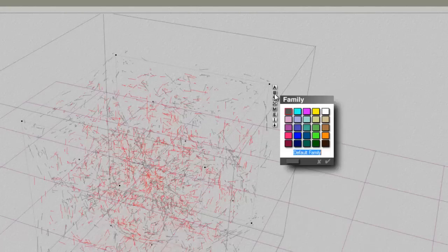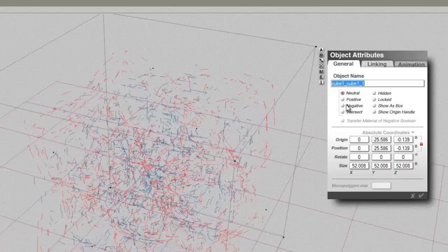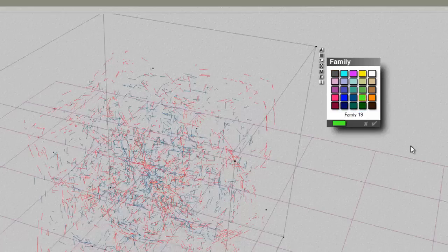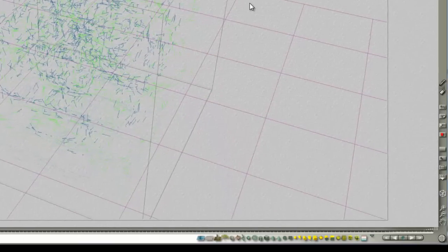And if you change the family grouping of that so you can identify it in the wireframe, and then hold the control key down, left click, and we've picked up the outer group, or the edge selection, let's call it. I shouldn't call it a group. Edge selection, and use a different family grouping for that, green. Okay, and the two objects are grouped together. If you change the family group of the entire group at this point, it'll reset all the internal groups, which is less than helpful. So we can use a family selection here. So there's the outer edge one.